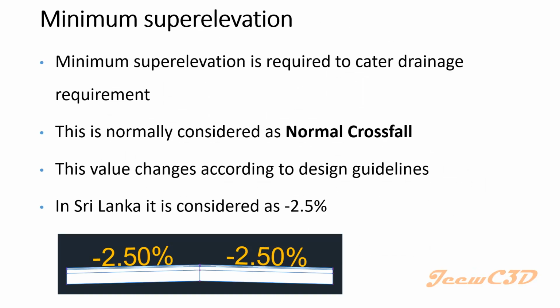We learned about the maximum super elevation. So what is the minimum super elevation you can have? What are the criteria we need to consider when you think of the minimum super elevation? The minimum super elevation is used to cater to the drainage requirement.